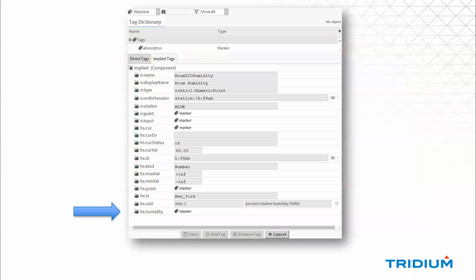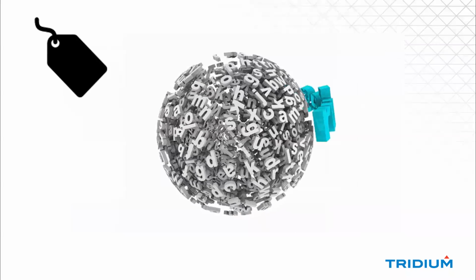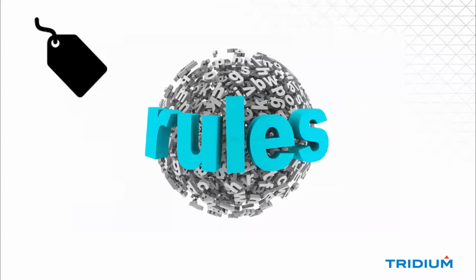So there's another methodology of tagging that implies these tags. You'll see here there's a bunch of implied tags for this particular control point, which is room humidity. And we'll see how I can use a tag rule to apply that automatically, so I don't have to worry about tagging.